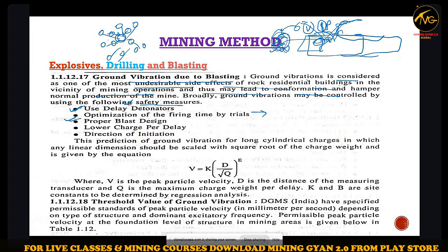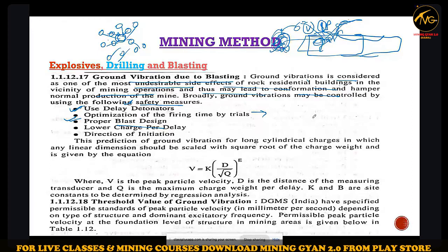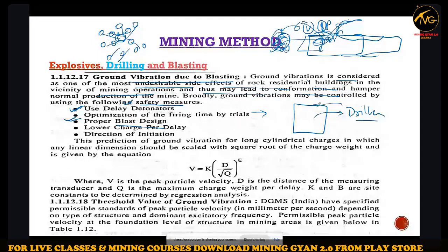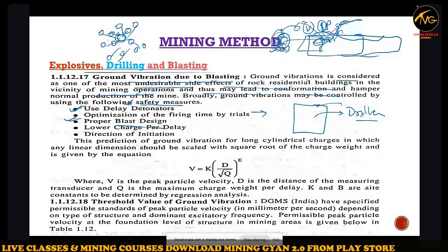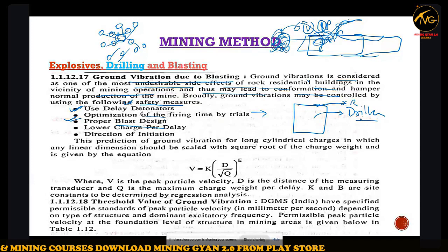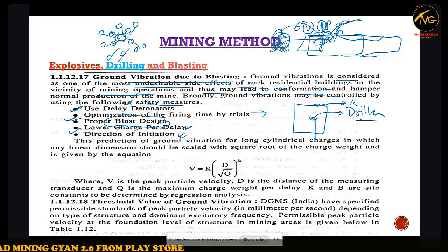Blasting design: choose which type of blast drilling pattern is suitable for your strata, which type of rock. So blast design is important. Charge per delay should be lower. Direction of initiation, where to blast from, where you should start. Threshold value of the ground vibration.